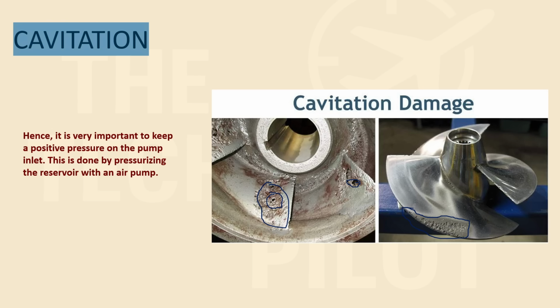And this is something that can be avoided if you keep the reservoir at a higher level than your pump, right? And that is why it becomes important. But on top of keeping the reservoir at a high level, you can also add positive pressure on this particular side.